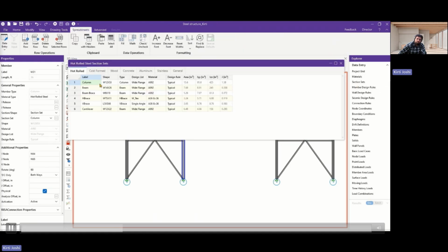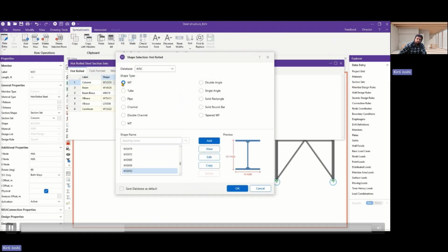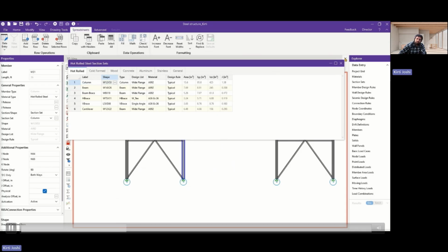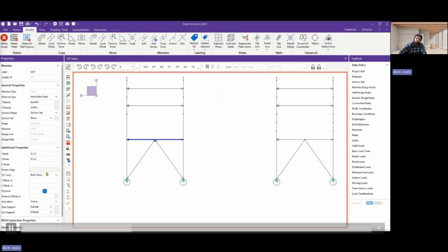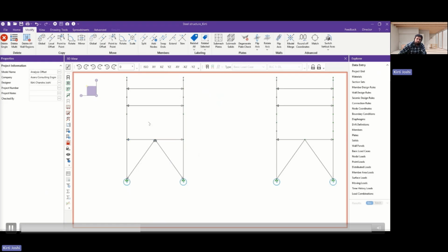Also, we are going to see these columns. The column depth is like 12, so we are going in the middle, so it is 6. We are going to offset it by 6 inches. So at the I end, we are going to write 6 inches so that it will shift. It will shorten my member.